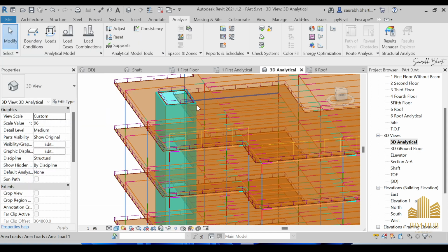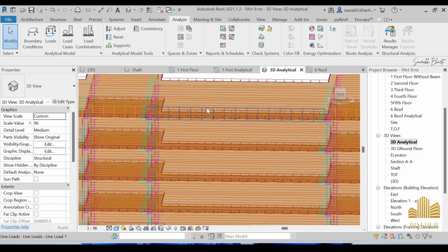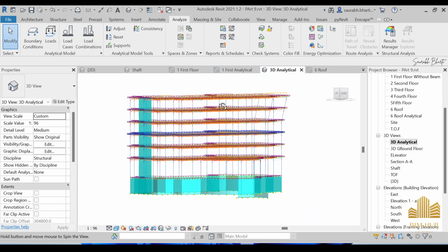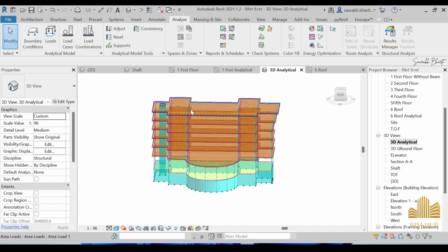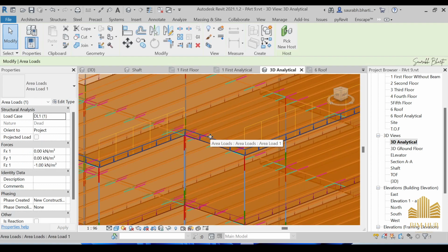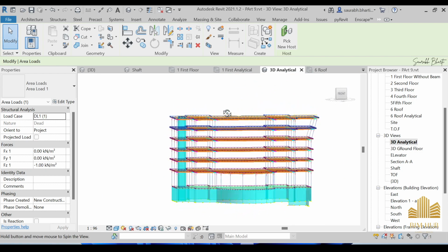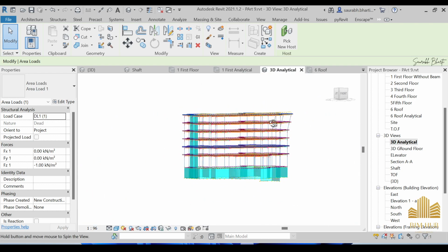And what else can be done is, if you have ever used ETABS, there's a software link to export this model from Revit to ETABS, and that is called CSiXRevit, I think. By that you can export your model directly to ETABS, and whatever changes you make live, whatever I change right now, will just show up in ETABS directly, and whatever changes you make to the ETABS structure will show directly in Revit.